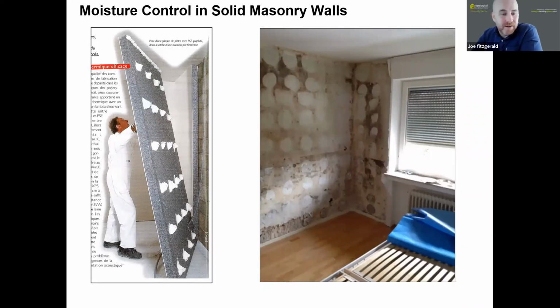So what happened was we started insulating everything like this. Now, not only are these boards highly impermeable to moisture vapor, I mean, they don't let moisture vapor evaporate through them, so potentially they trap things behind them. They also created still air pockets in the zones between the dabs. Those still air pockets provided a space where warm, humid air could leak in from the room side. And when it did, it would find that cold, uninsulated surface. Because there's not adequate ventilation back there, it had the perfect conditions for mold growth.